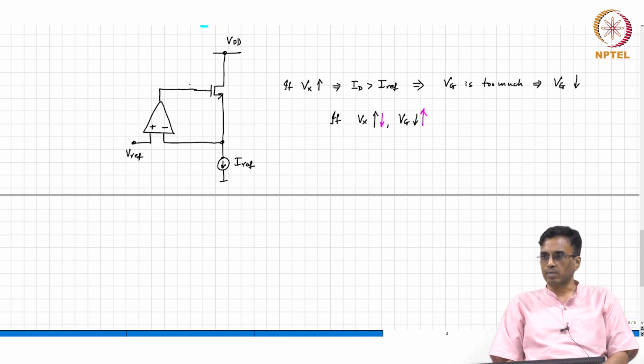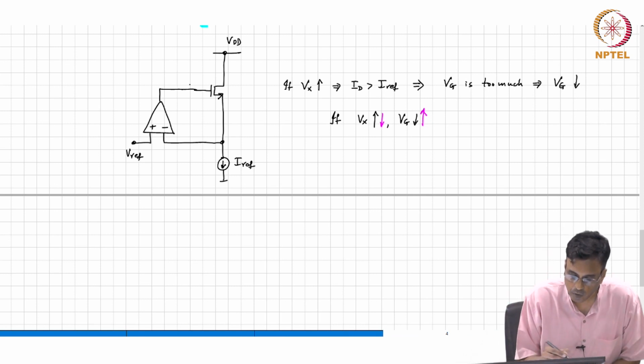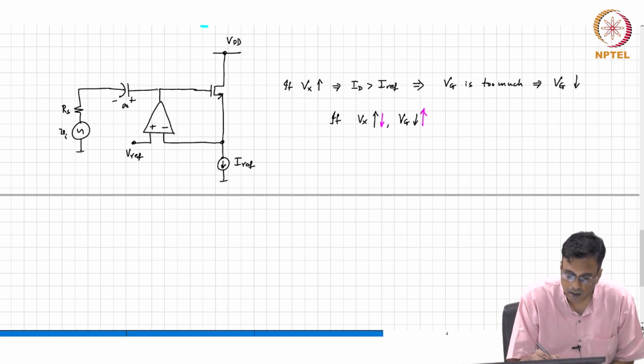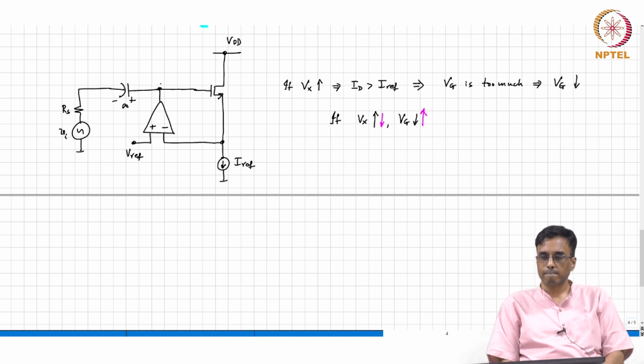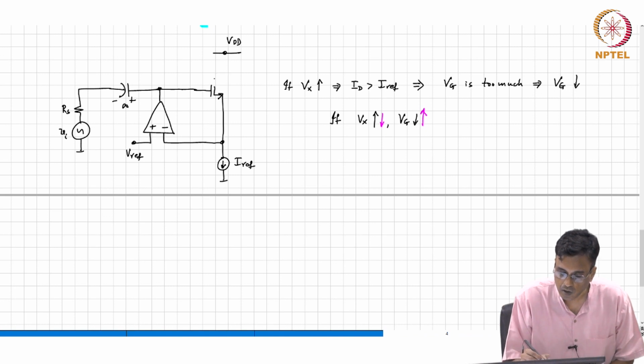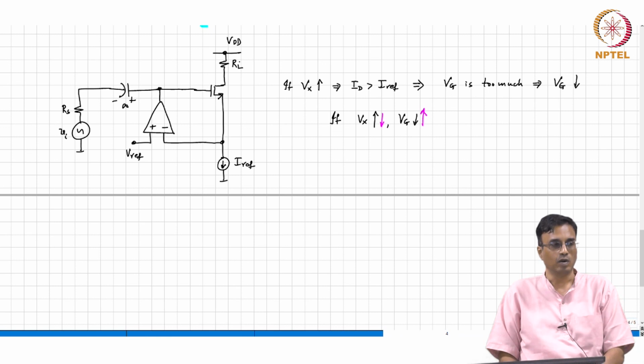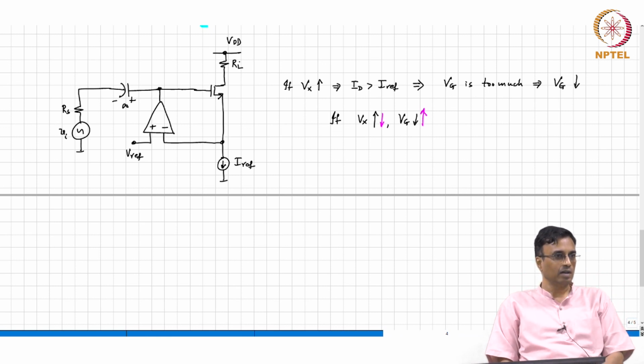Now, what are we going to do? We need to make a common source amplifier, yet another one. Now you should be able to tell me what I should do to make this a common source amplifier. What should I do? Okay. So, basically we add the infinite capacitor here. Again there are multiple ways of doing that. You can put an inductor there, or put the load resistor right there, or if you do not like that, you can couple it with a capacitor, the usual thing at the load.